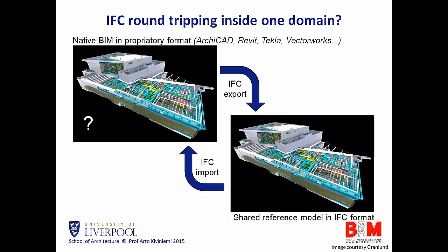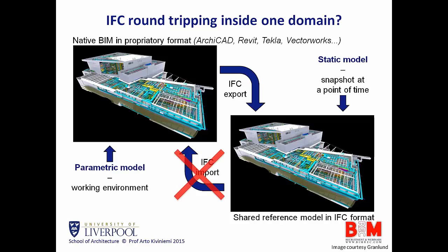People expect that it should be the same model that you exported, but it's not. First of all, the environment where we are working is a parametric model. It's our working environment. When we make the IFC export, it's creating a static model. It's no longer a parametric model. So it's a snapshot at that time.